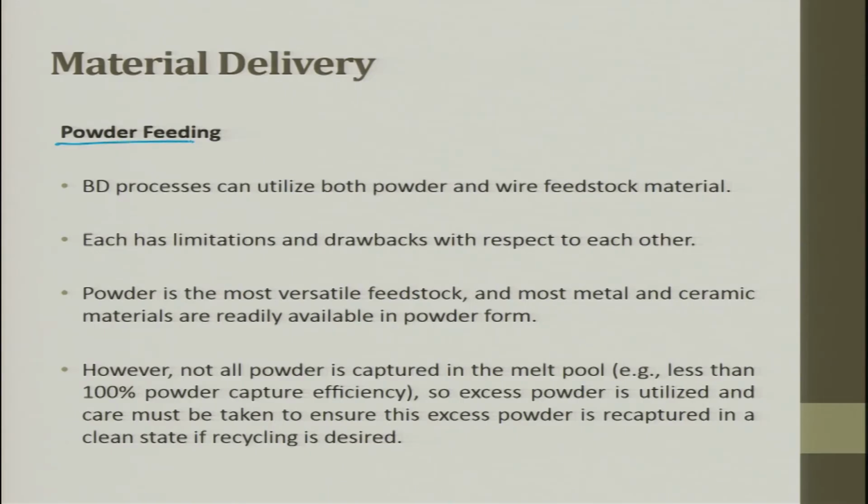Powder feeding is a very challenging task. Because the powders are smaller in size, they can easily fly off, they can easily get agglomerated. When it agglomerates, it clogs. So powder feeding is a huge challenge, and if you have multiple different varieties of powders falling, the flow rate between them has to be controlled.